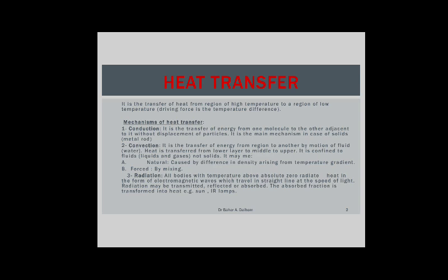Number two, convection. It's a transfer of energy from one region to another by motion of a fluid, like water. Heat is transferred from the lower layer to the middle to the upper. It's confined to fluids, liquids and gases, not solids. It may be natural or forced by mixing.